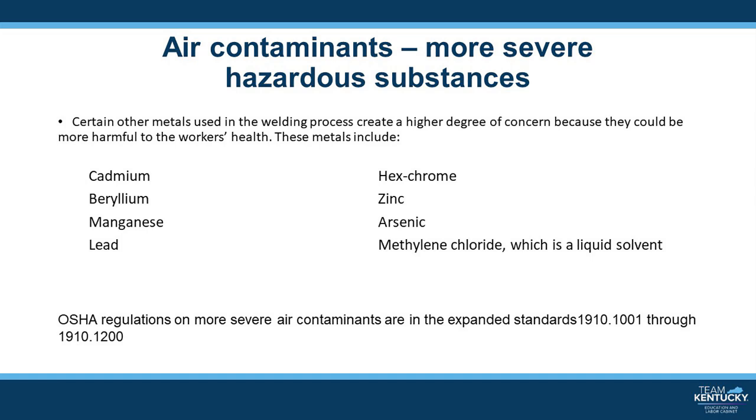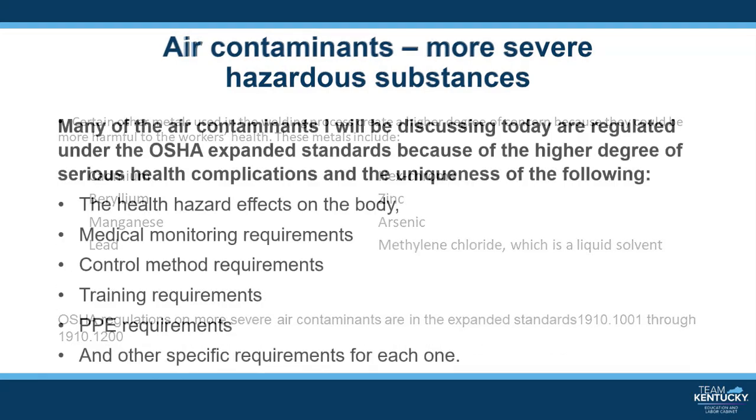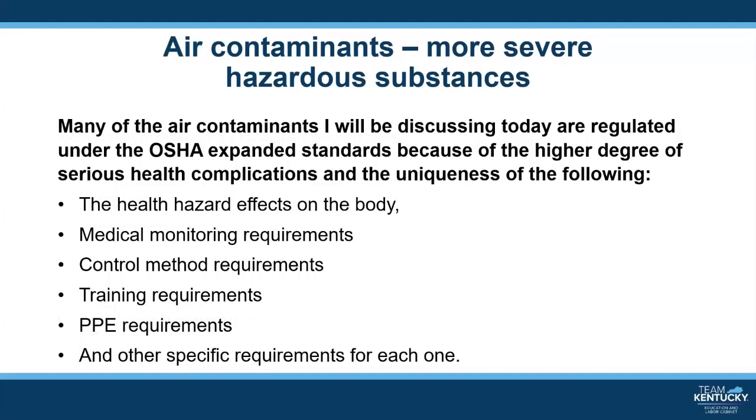There may also be other particles in the air in the welding environment, such as asbestos, that can be in the air where you might be welding. Many of the air contaminants that I will be discussing today are regulated under the OSHA expanded standards.